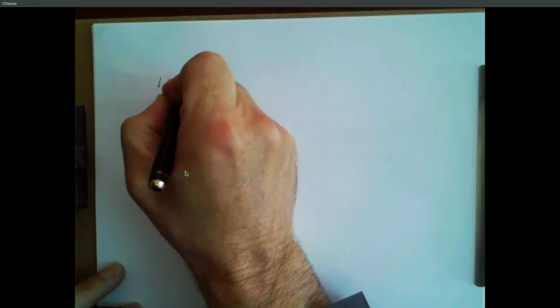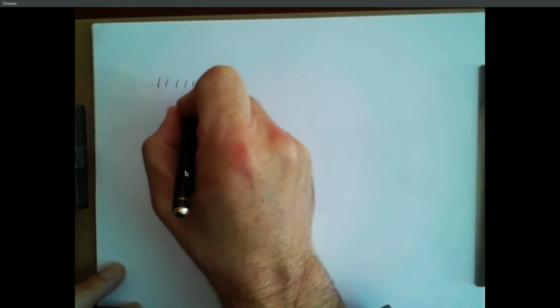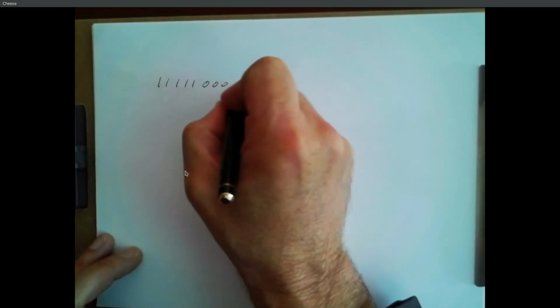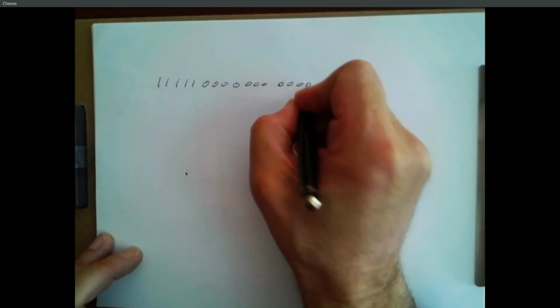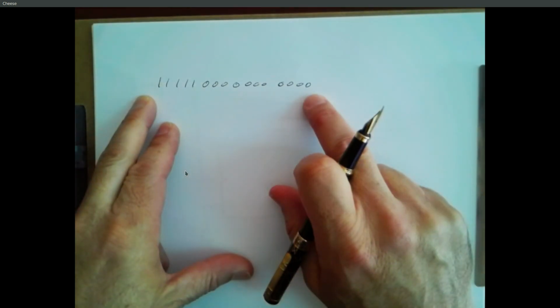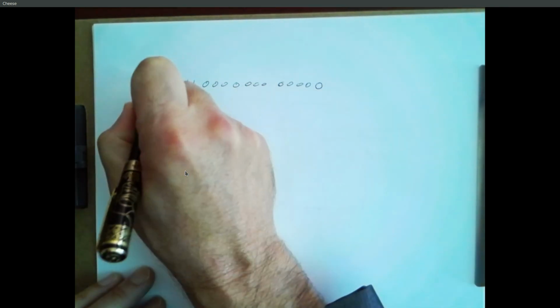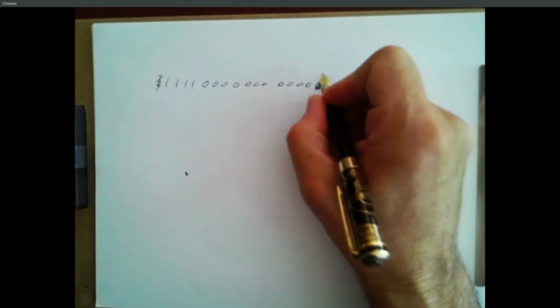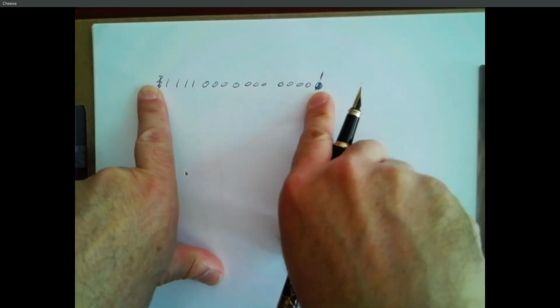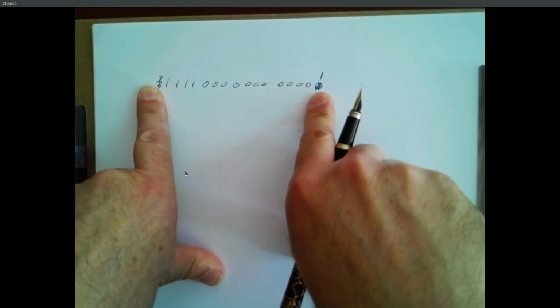Because if you get a 1 here, let's say you get 5 ones. I'm going to go right to left instead of 0. So at this point we'd have 5 ones, and I'm going to guess that that's 16. It might be off by 1. So now, 16 events, we had 5 ones. Our output should still be a 1. The next time that we get an input, that one falls off the window, and now our output should be a 0. But if this input had been a 1, now we would say, okay, last 16 events, we've still got 5 ones, so our output would still be a 1.